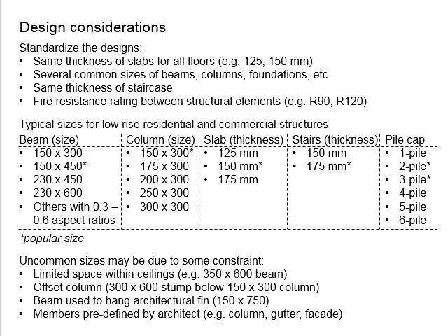Based on the dimensions given in the technical drawing, they know how they're supposed to construct the formworks for the placement of the reinforcement bar, and then get ready for the casting of the concrete without any leakage, without any undesired deformations of the formworks that can result in different shapes and sizes of the structural elements.